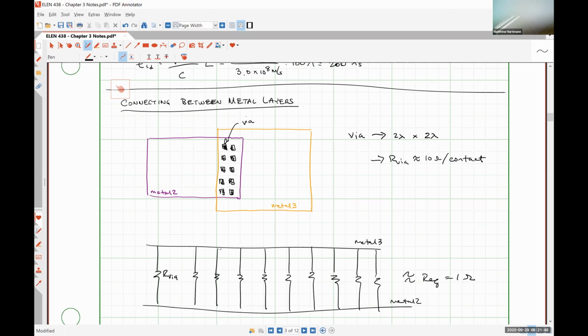And one way to allow that to happen is something that we talked about in last class, where we use very wide wires, which will lower the overall resistance of our wires because we'll have less squares to account for. And that also enables us to put multiple vias in to lower the contact resistance between the metal layers. Okay, so I believe the last couple of topics that we're going to discuss with regard to the metal layers are some of the kind of negative effects that we need to be on the lookout for.